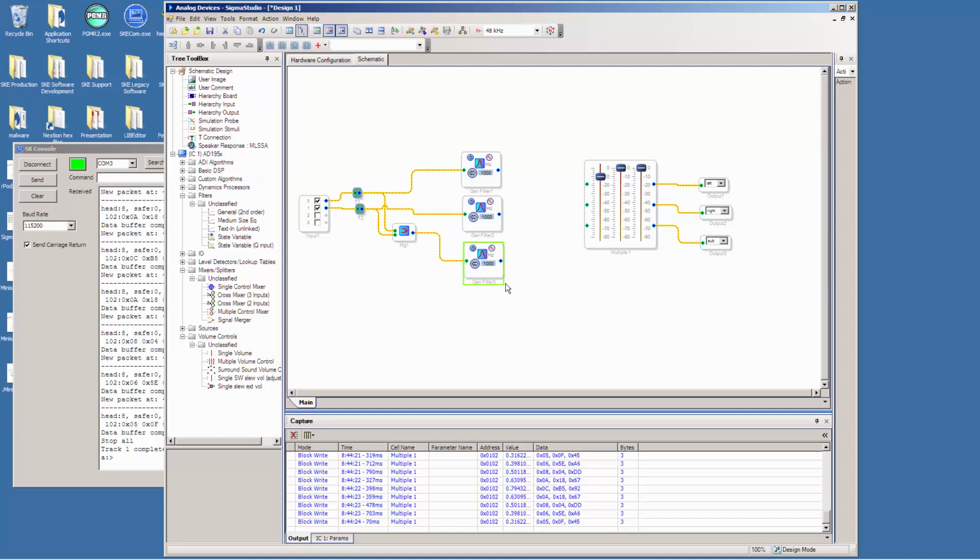So for the sub, we're typically going to have a low pass filter. So I'm going to go ahead here and select general low pass filter. We'll set the frequency down at say 100 Hertz. And we'll leave the Q there at 1.41. For these, I'm going to go ahead and put a high pass filter in.